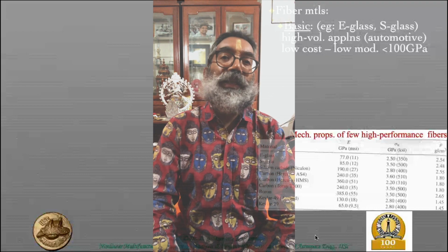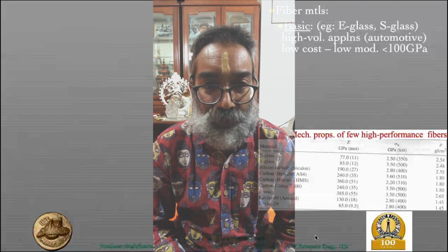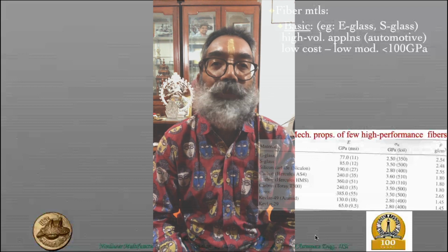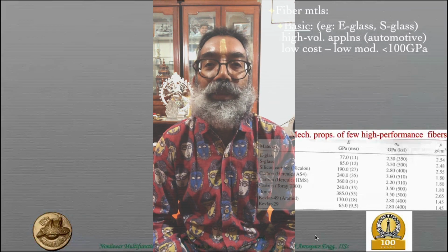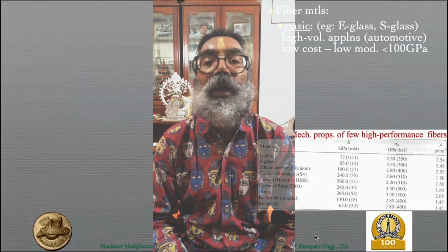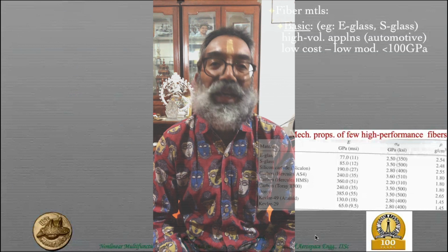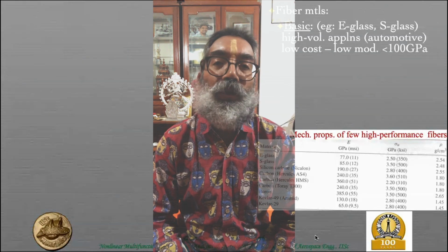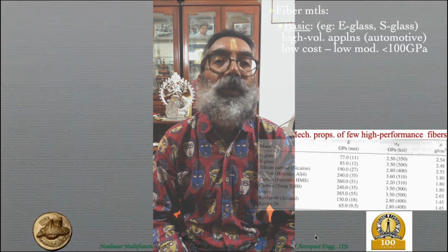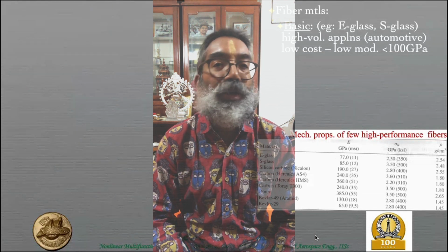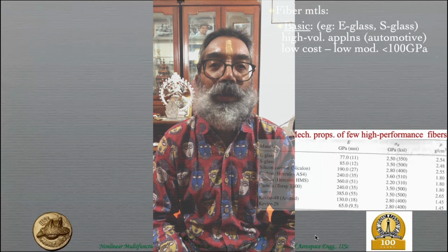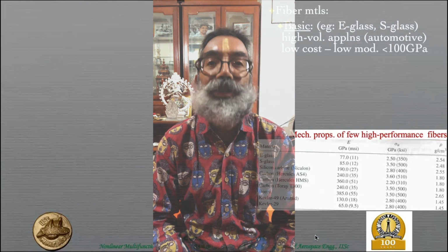Very good. It's an excellent question. See, in fact, these are all experimental based failure criteria. You test the material and then you come up with certain strengths, etc., and then you develop it. And when it's a multi-axial kind of a situation, you will have what are known as failure envelopes, where when both the loads are present, failure can occur when neither of those loads have reached their own ultimate or even yield levels. So that is basically what that kind of a situation is.